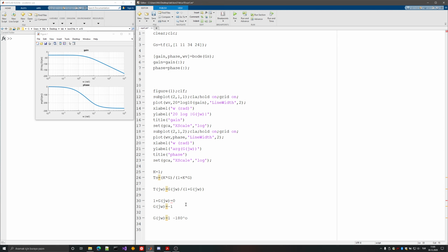So basically, the system should satisfy two conditions based on this. The absolute value, or the gain, should be 1, and at that exact frequency, because we have a fixed frequency here, omega star, if the gain is equal to 1 and the angle is equal to minus 180 degrees, then we have a division by 0, which will give us infinity. And basically, even if I apply a bounded signal to the system, even a constant, the output will tend to infinity, which is basically our definition of instability, which means that up to this point we will have a stable system, because I'm increasing omega and the stuff changes, but I am crossing 1 and minus 180 degrees. But keep in mind that k is not equal to 1.